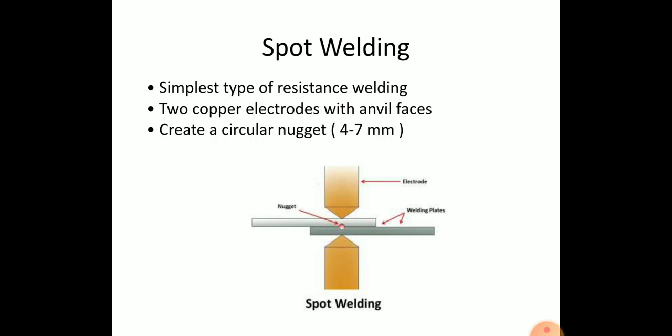Procedure: first, the job should be clean. It should be free from gases, dirt, paint, scale, oxide, etc. Clean the electrode tip surface very fine. Emery cloth may be used for routine cleaning. Water is kept running through the electrode in order to cool the weld and avoid the electrode overheating. Proper welding current is set on the current selector switch. Proper time is set on the weld timer.